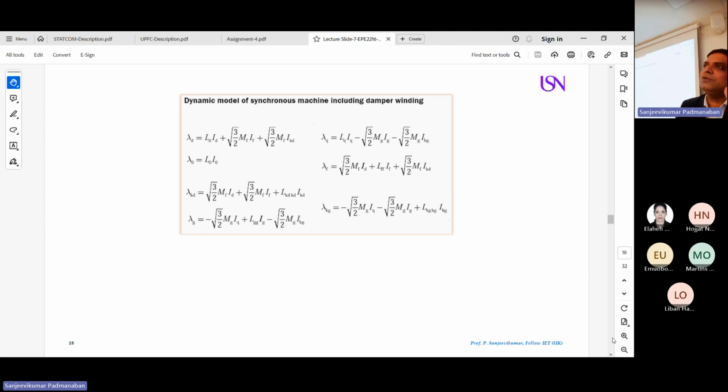Because of that, you also create sparks. When you have a DC machine and you go to the lab, you find sparks in your brushes. The reason is armature reaction. That is the first case. Second, maybe you can have damage in your brushes, etc. These are the major reasons why you get sparks in your electric machine. The same will happen for your synchronous machine.